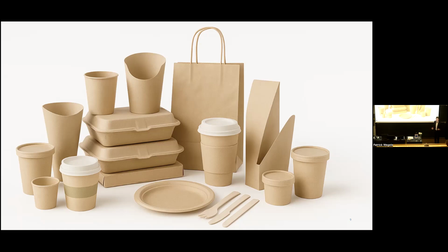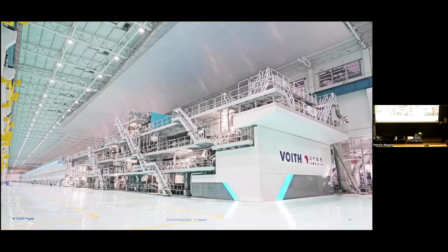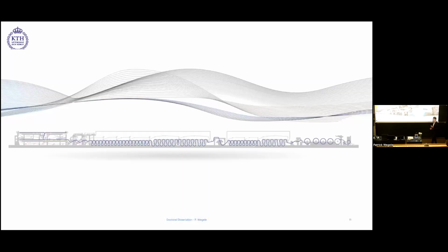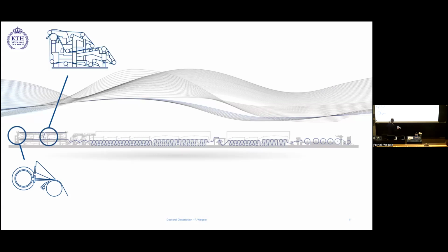Within an industrial scope, this is done in a so-called paper machine. The paper machine that you can see in this picture is a huge and enormous machine that looks rather complicated. However, the process of paper making is rather straightforward. You basically have a suspension of cellulose fibers and water that you apply using a head box on a so-called wire, where the initial sheet is formed. Afterwards, you transport this wire through a so-called forming section, where vacuum dewatering is used to further increase the solids content of the wet sheet.